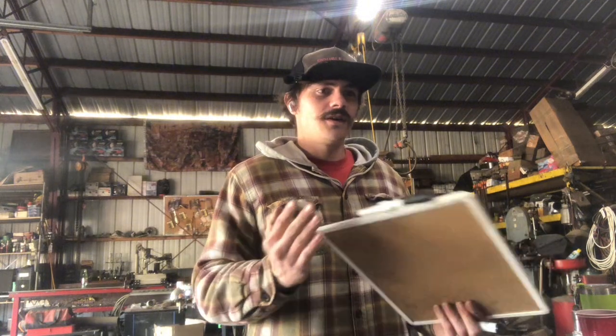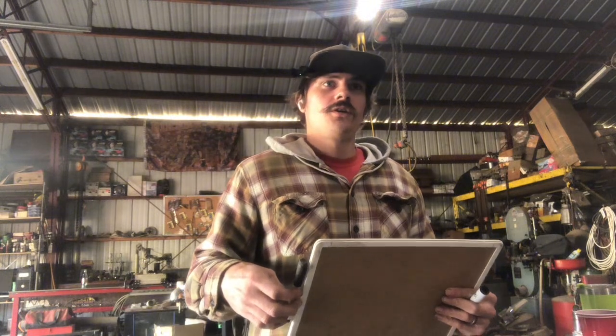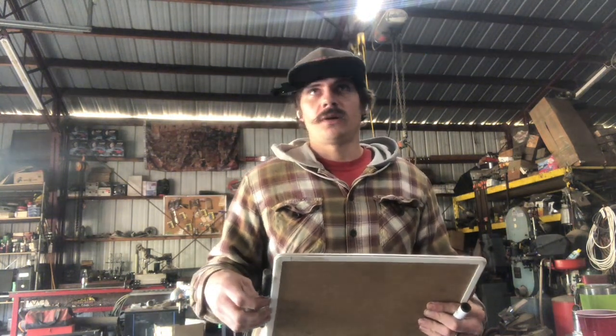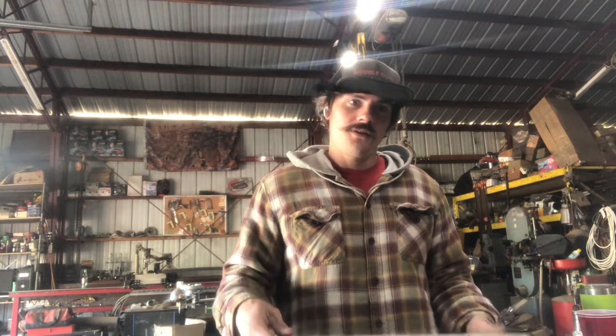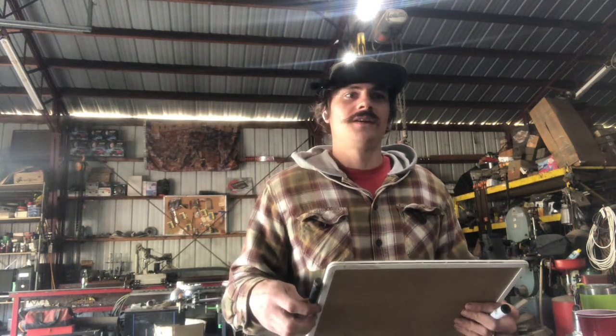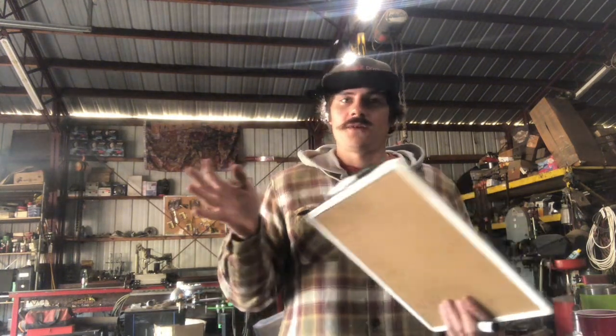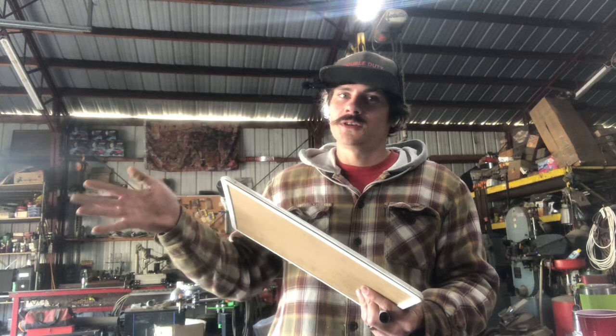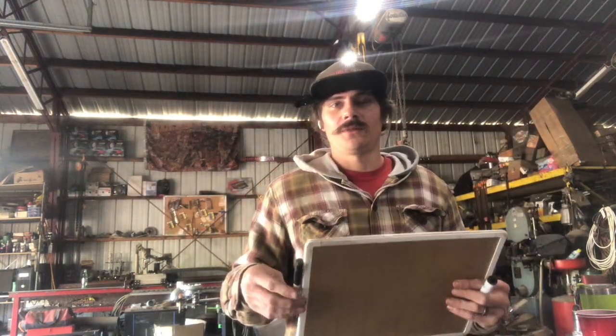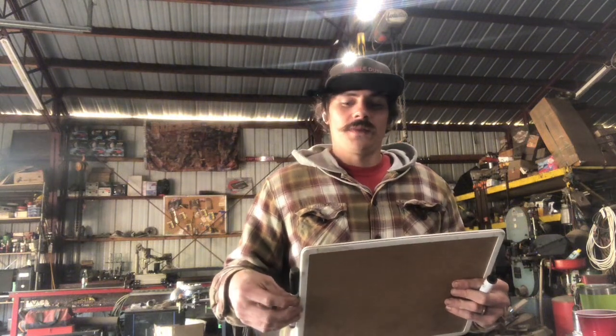This is really complicated at first because there's not a lot about it in the automotive industry, performance-wise. We get preached compressor map, compressor map, compressor map. The compressor map has nothing to do with the turbine map. Well, unless we factor in the rotor speed, but you can have a compressor running at 80% efficiency, and a turbine that's royally unhappy at 40% efficiency. That is definitely something you can have. So it's not talked about.